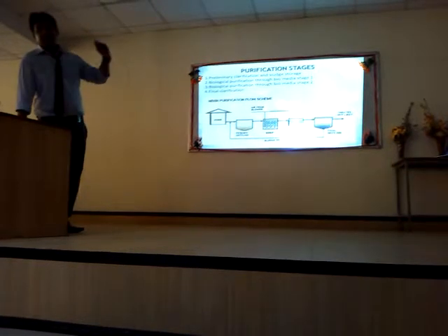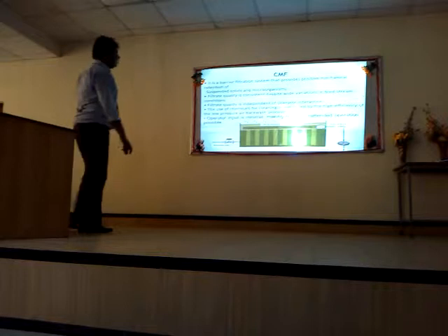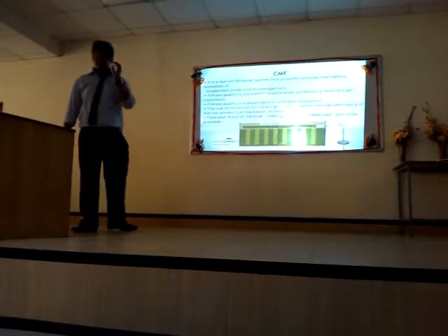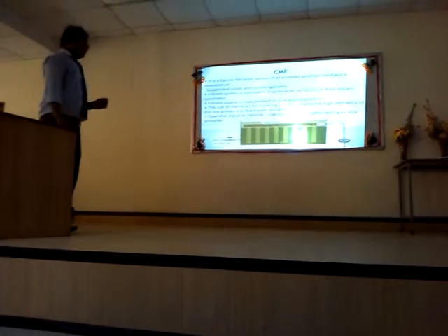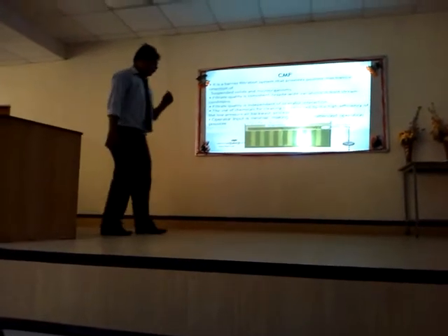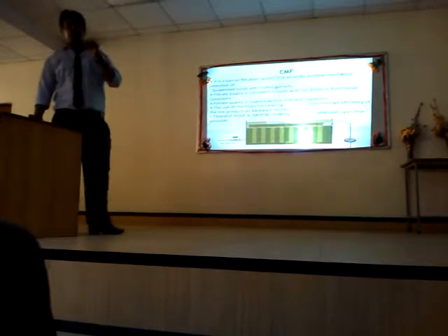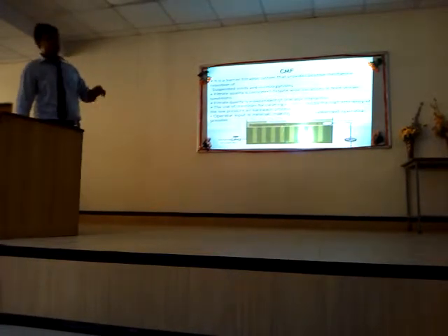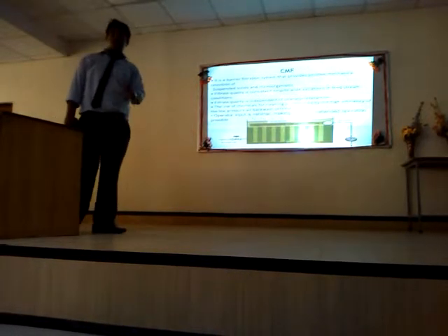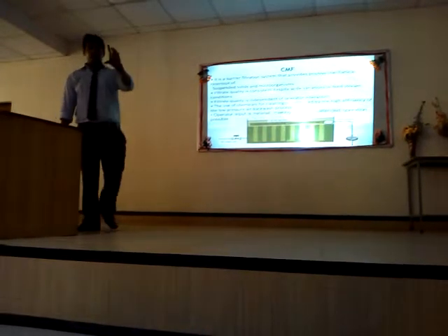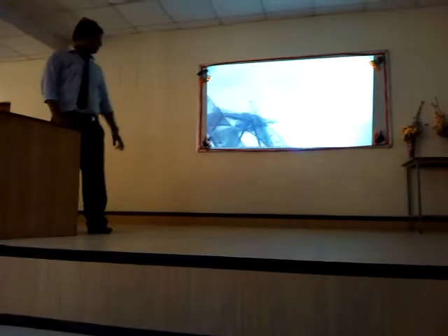After that this water is treated in CMF. Now CMF, as I told you, is continuous membrane filtration. It's a membrane made up of very fine fiber, which filters up to 10 micron. So after being treated by CMF, the water is approximately the same as what we find in packaged drinking water like Aquafina or Cleanly.